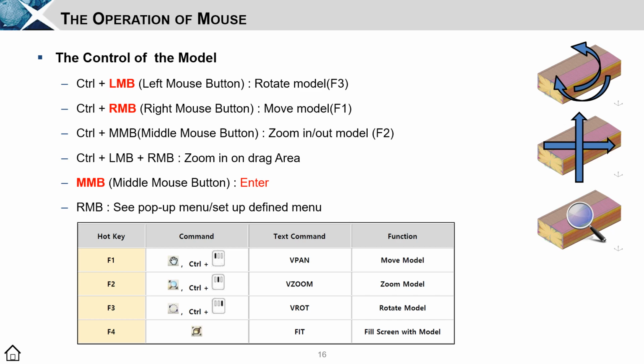The mouse wheel button is used to execute commands with the same functions as an enter. The right mouse button is used to display pop-up menus. Zoom in, zoom out, and orientation can be set by the user on the Display Options View tab.